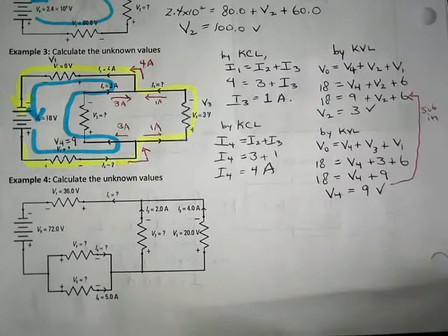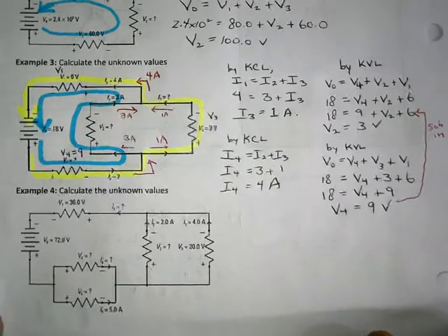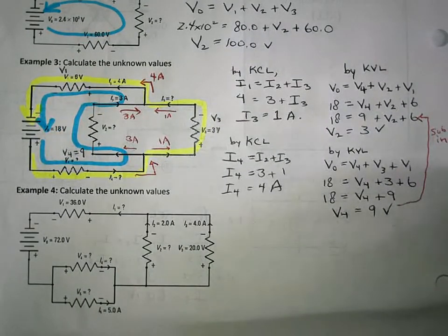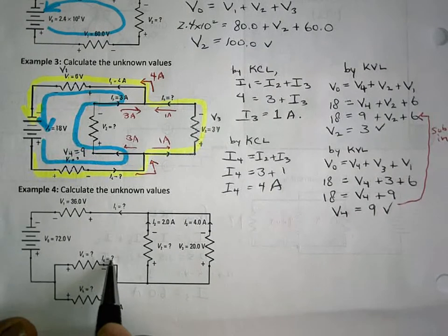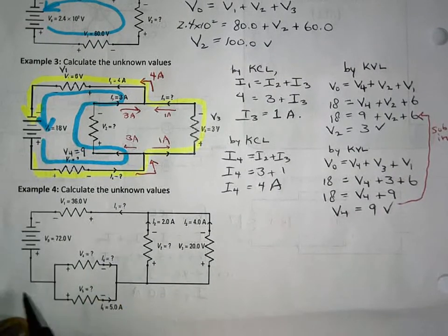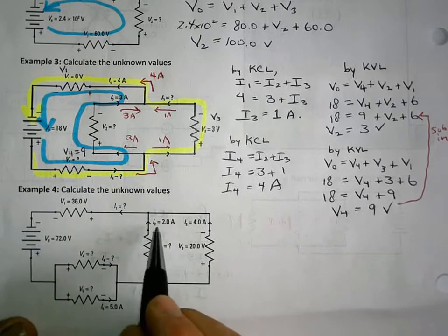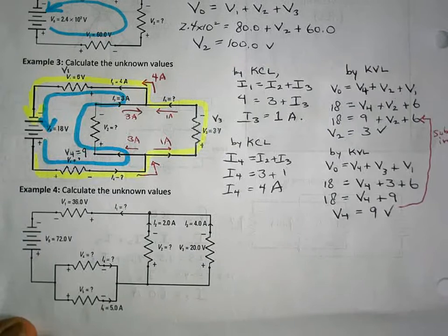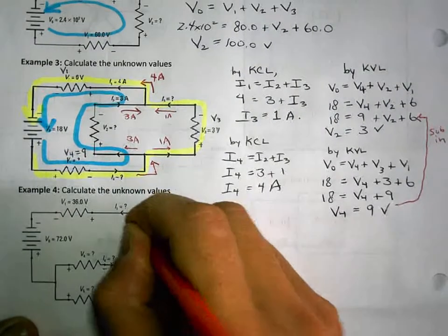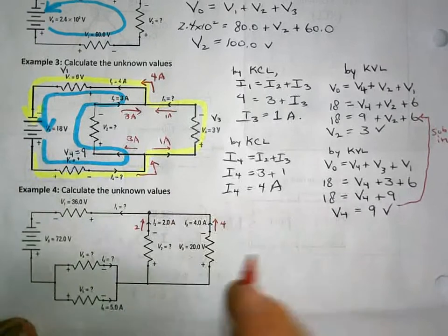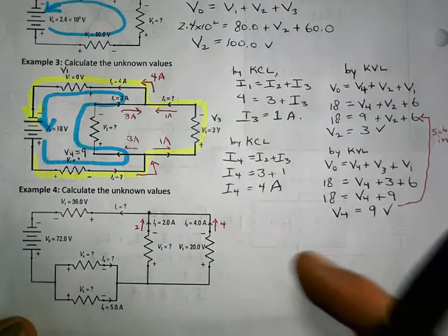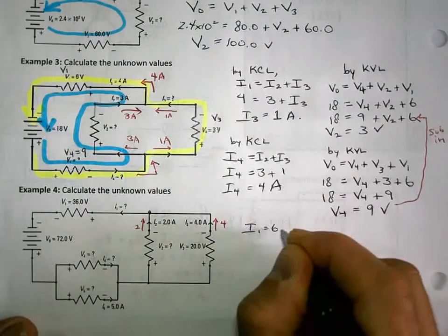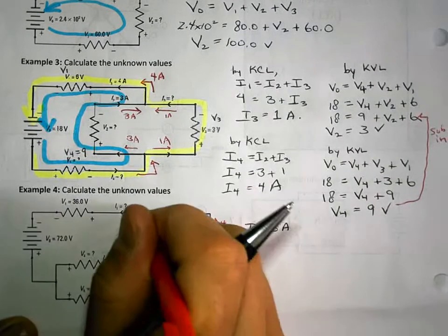Okay, let's try doing this last question, and this time we're going to do it a little bit more by inspection. Let's again start with current. That's my favorite one to work with. So here we have 5, and then we have some unknown. We don't know how much is here. Okay, this looks like a good node here. I can draw 2, 4, and an unknown amount. So 2 plus 4, so I1 has to be 6, because those combine to form 6.